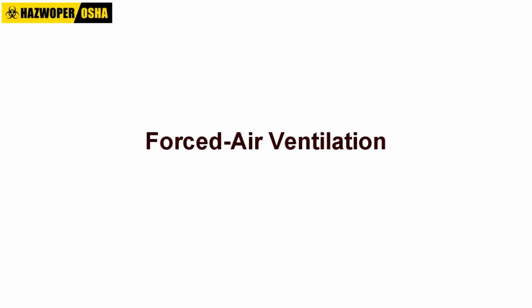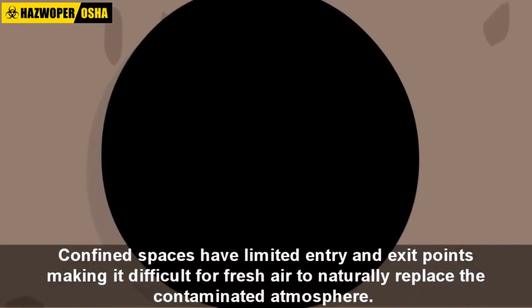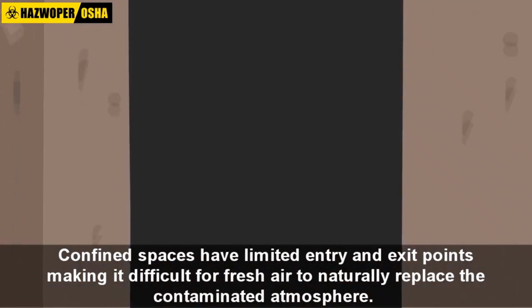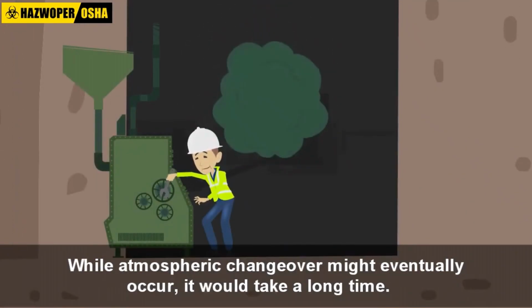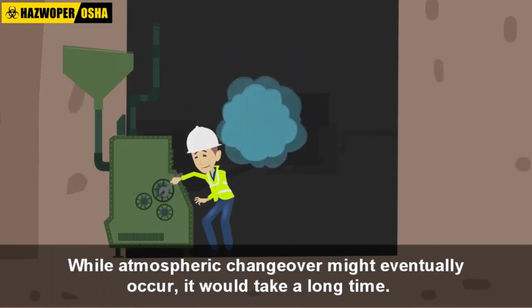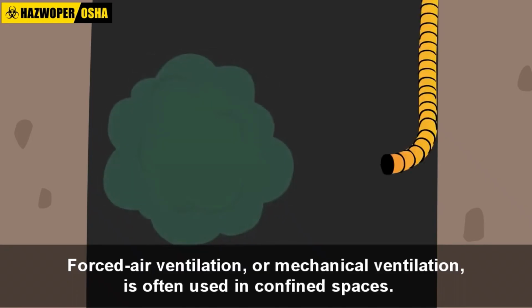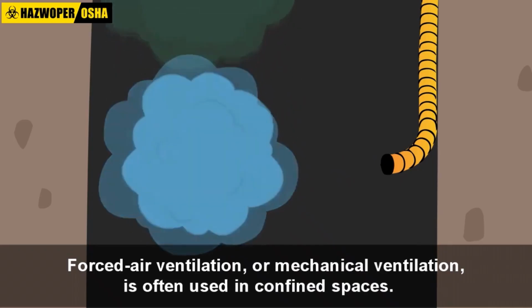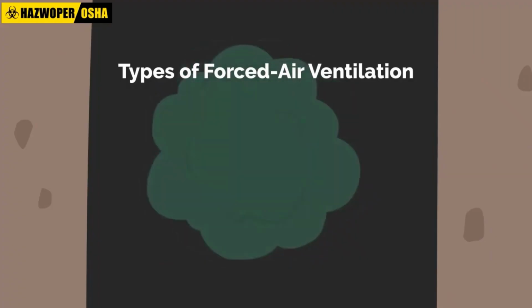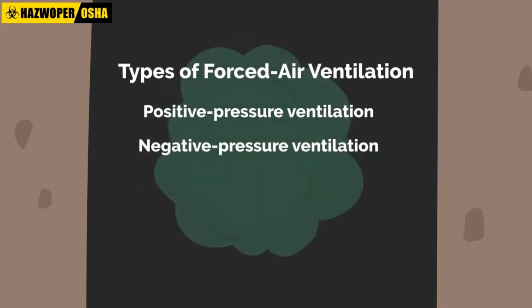Forced air ventilation. Confined spaces usually have limited entry and exit points, which make it difficult for fresh air to naturally push out and replace the contaminated atmosphere. While atmospheric changeover might eventually occur, it would take a long time. Therefore, to speed up the process of replacing contaminated air with fresh air, forced air ventilation or mechanical ventilation is often used in confined spaces. There are 2 types of forced air ventilation: positive pressure ventilation, and negative pressure ventilation.